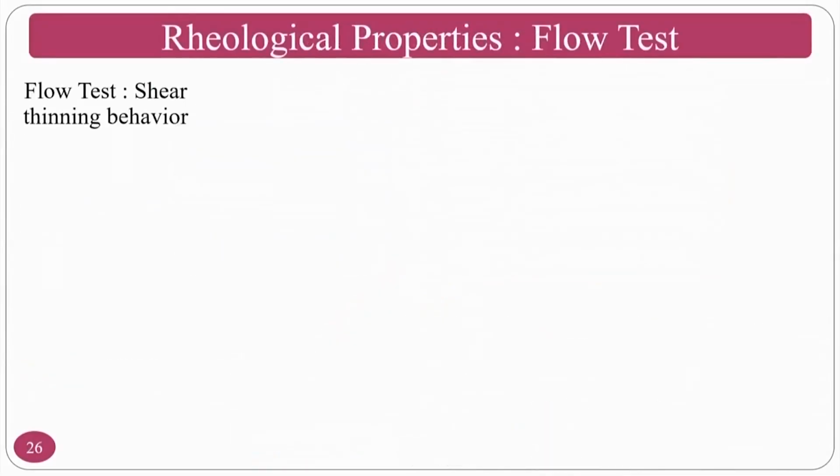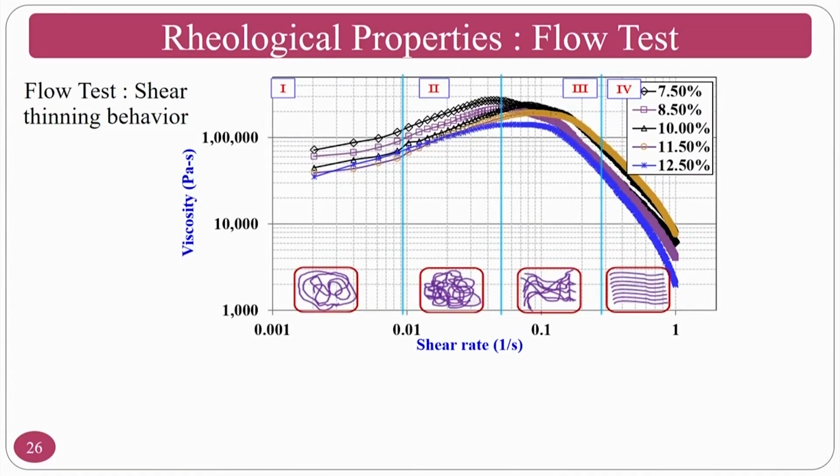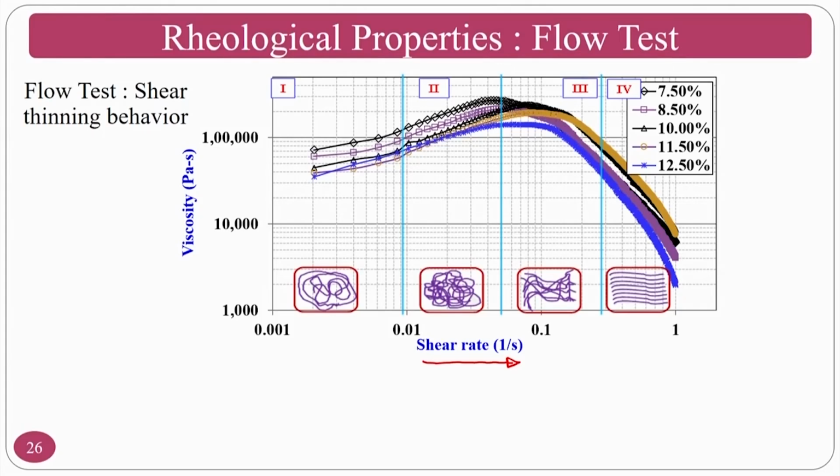Okay. So, if you see the analysis, as the shear rate increases, what is going to happen here is the abrasive medium will experience more rotational effect from the tool master. If you see any curve, what is happening is, when the shear rate is low, that means that your top rotating plate is rotating at slower speeds, because of which what will happen is your polymer molecular chains climb one over each other and resist the flow.